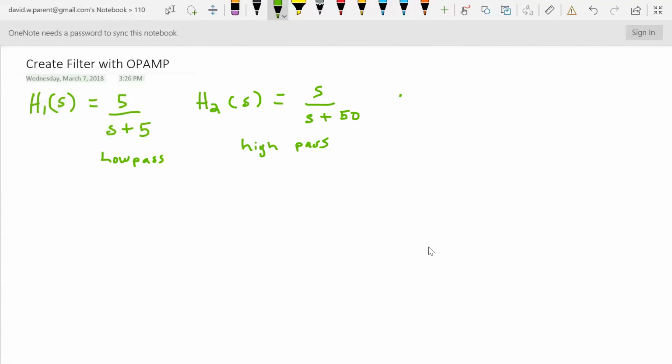There's more than one way to do anything, right? There's low pass filters that are inverting, and then you put them through an inverting amplifier, right? But when I see this, I tend to just go for this simple structure, because I know that we're going to be chaining and adding. We really need to put a buffer here. Otherwise, everything will start affecting everything. Then here we have the high pass.